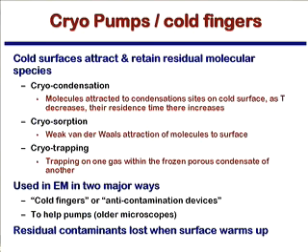Another thing that people use in the electron microscopy world very frequently to help with the vacuum is some form of cryopumping. In the case of the microscope, usually what you have is a little metal cold finger, they call it. It's just a little piece of metal that's very close to your sample, and you cool that with liquid nitrogen. And the idea is that if you have stuff floating around your sample, it'll look at that cold surface and prefer to go there through one of these mechanisms and stay there, thereby keeping the area right around your sample very clean through the use of this additional pumping mechanism, cryosorption or the like.